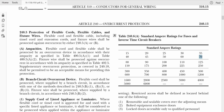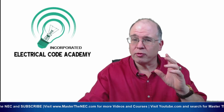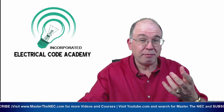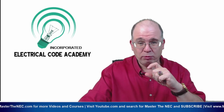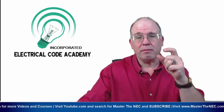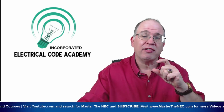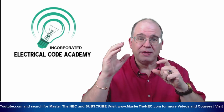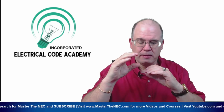Now, why is this important? You need to remember this, because at some point, we're going to do a calculation and we're going to determine what a new ampacity is of a conductor based on the ambient and the number of conductors. So we're going to get a new value. Ultimately, one of the last steps, and the reason I cover it as the first step, because we got to come back around and look at it at the end, you're going to compare now and see, well, this conductor's new ampacity, this is what my breaker has to be. This is what my conductor's ampacity has to be.